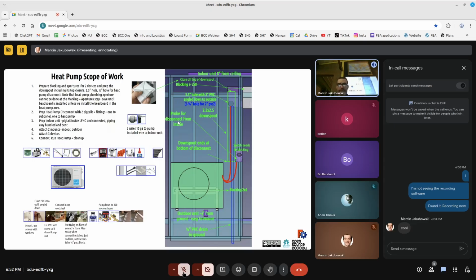The scope of work is, one, you physically connect and mount everything. Two, then you wire it up. Then three, the major third part is you have to vacuum pump the system to allow the refrigerant to escape into the indoor unit. Because typically these heat pumps, the way they come these days, the working fluid is under pressure inside the exterior unit. So you have to let it out. Just turn the valve and let it out.